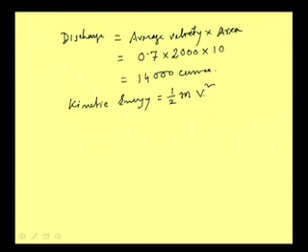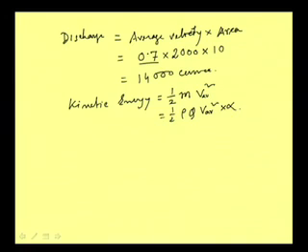Now, this v is the average velocity, which we have already got as 0.7. So, this mass is nothing but rho into q, and the kinetic energy is half of rho into q into V average square. Now, if we calculate the energy straight away like this, it will not be correct. The reason is that, because the velocity is varying, we need to multiply it by alpha. So, our correct kinetic energy will be this multiplied by alpha.